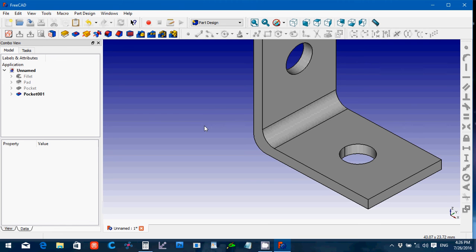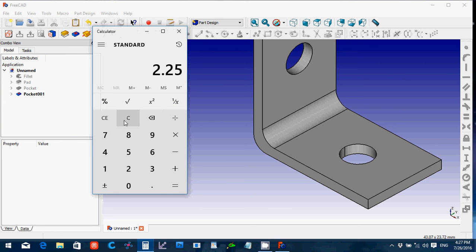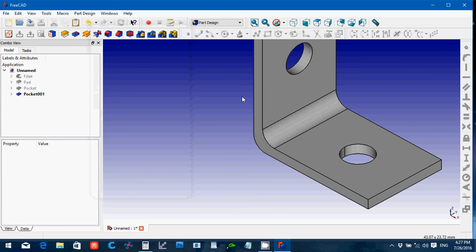So let's say the original hole, the outside part will be 6.5, right? 6.5, and the internal part was 4.5, so we're going to subtract 4.5. So you got a 2. That means your chamfer probably should be divide that by 2 equals 1. So it'll be 1 millimeter chamfer.